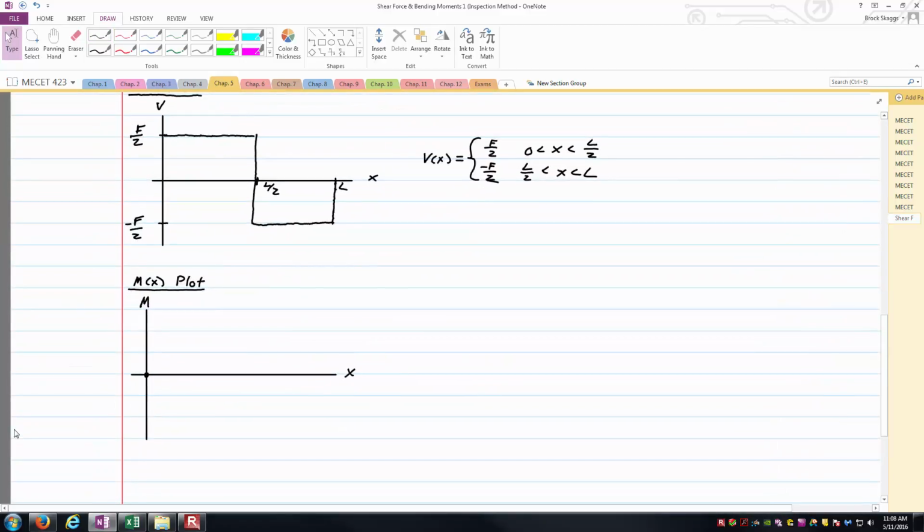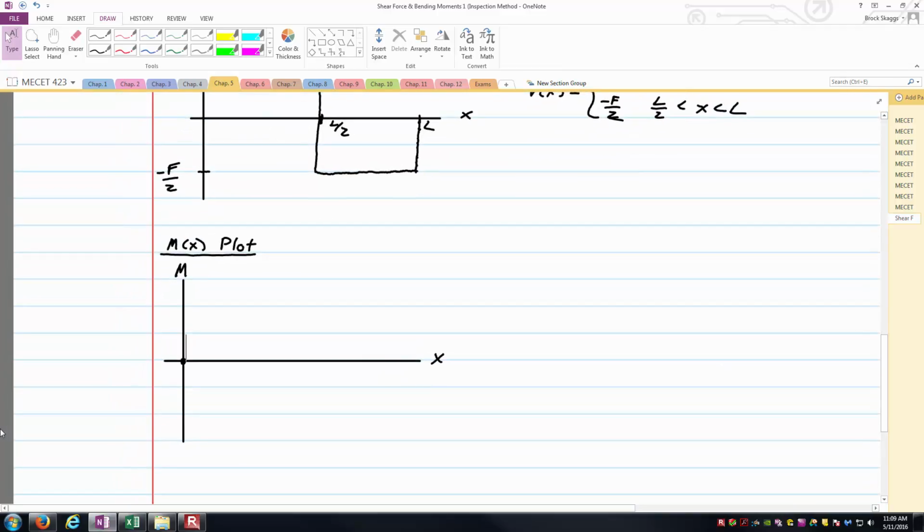And so the relationship part of this that we need to know is that there's basically an integration happening between moving from the shear diagram to the bending moment diagram. And so that is the idea here. Actually, I'll go ahead and write that in the margin here. So what I'm thinking is, well, dM/dx is equal to V, and so some change in M, if you want to think dM, is V times the change in x, or another way to think of it is M is the integral of V of x dx here. And I'm sure there'll be videos coming where I'll expand upon this idea a lot more.